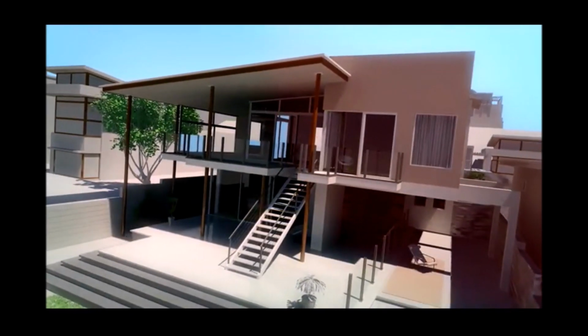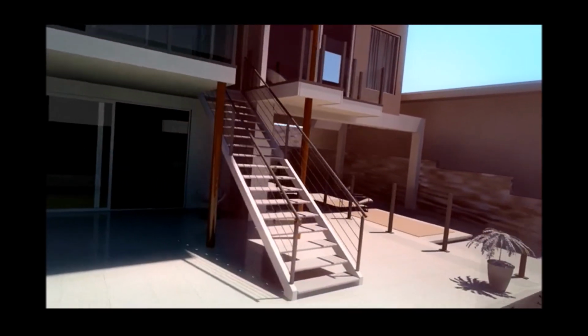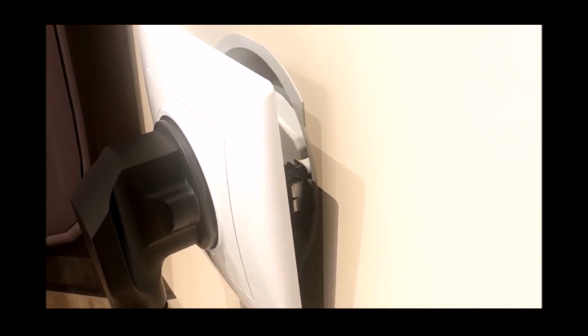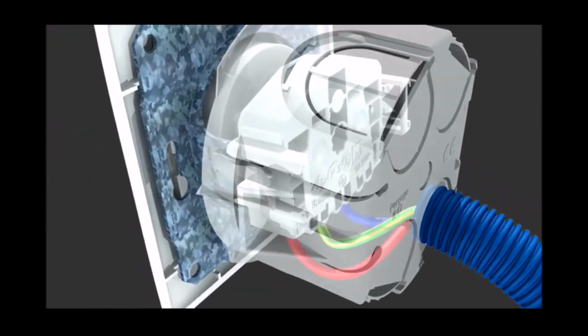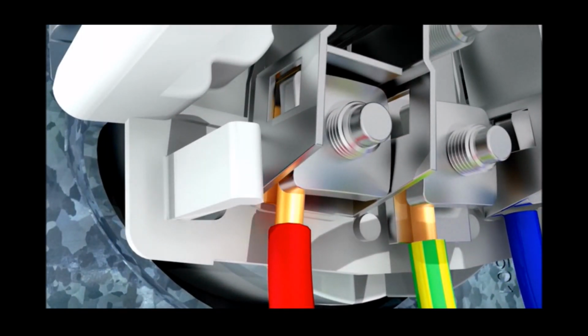Electrical fires can also be caused by localized electrical faults. These could be due to an overloaded cable or socket, or an improperly installed socket. Any of these factors could cause connections inside the wiring to break down, triggering a fire. How? The connections gradually pull apart and overheat, burning the surrounding cable insulation and socket.